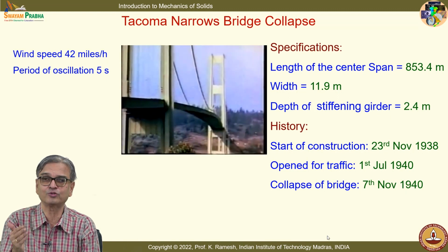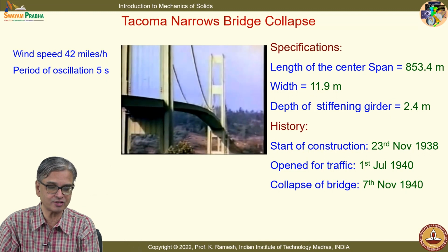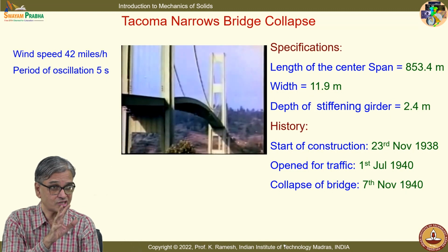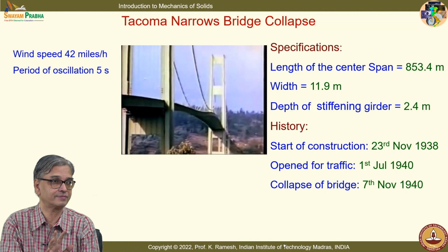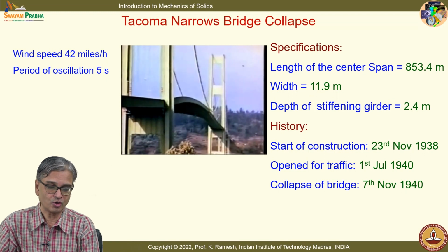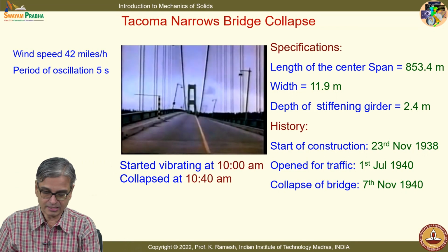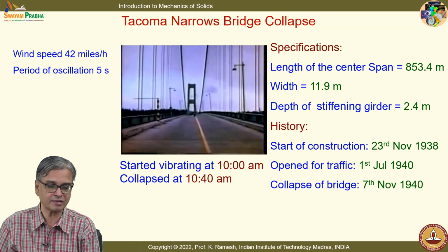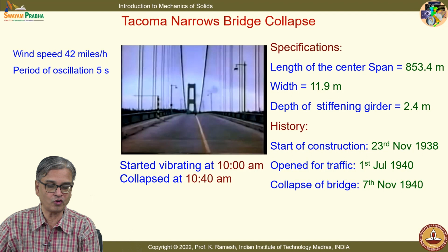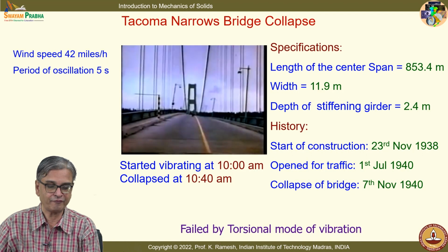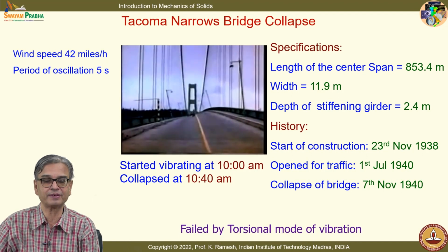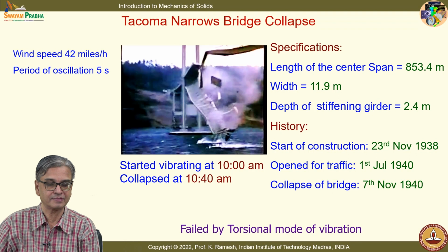So, that led to development of cross bracings to sustain the wind loads. Okay. So, what you had was, it started vibrating at 10 o'clock, vibrated for about 40 minutes, and it failed by torsional mode of vibration. Fortunately, there was no major casualty except one car was falling into this.